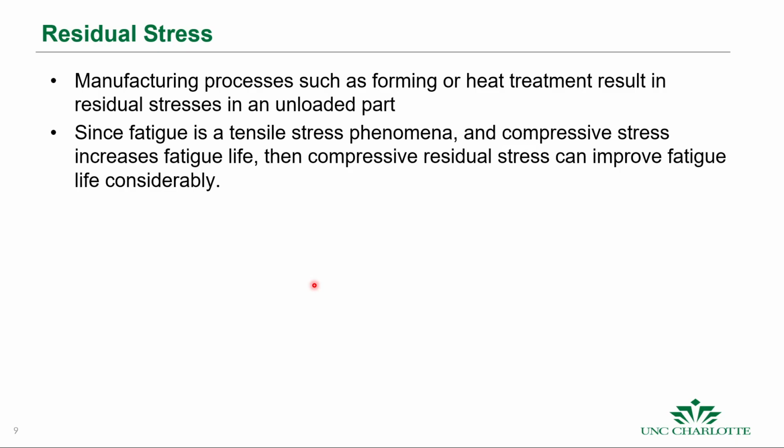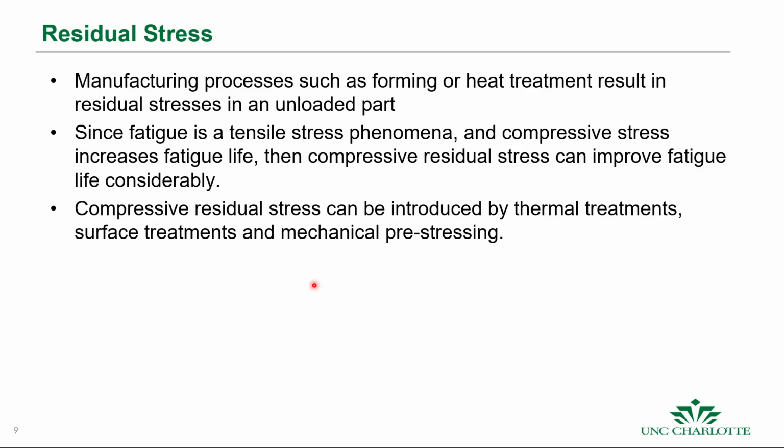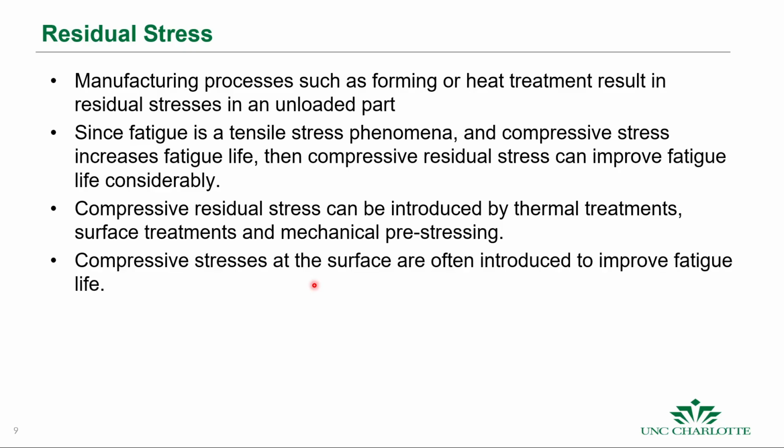Since fatigue is very sensitive to tensile stress, and it benefits from compressive stress, in other words, fatigue life is improved with that compressive stress, then compressive residual stresses can improve fatigue life considerably, and tensile stresses can reduce fatigue life considerably. And we can introduce these compressive residual stresses either by thermal treatment, surface treatment, mechanical pre-stressing, or cold working. Compressive stresses at the surface are often introduced to improve fatigue life.